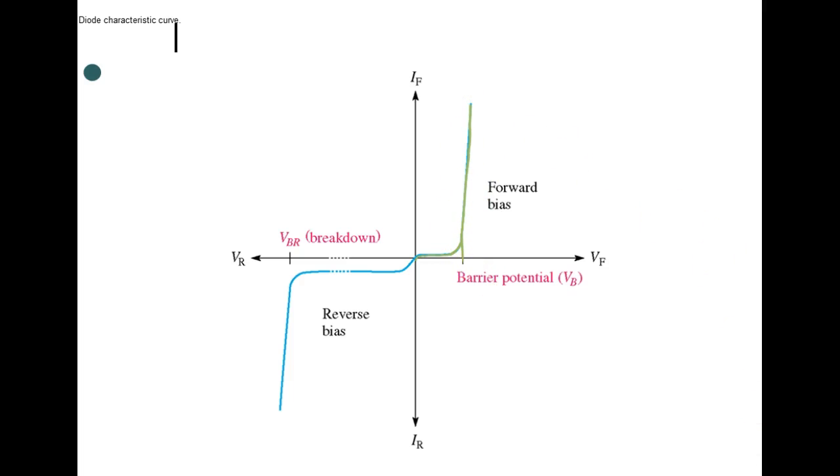Everybody understand why it don't go straight up? Because there's an R component inside the diode. So the more current you put through it, the more voltage drop. So one of the ratings we'll look at, they call it VF max. And of course, this will be the maximum voltage. That should be the voltage you expect to cross it when you're conducting the maximum current. If you're below that current, it's going to be below that voltage, right? You understand?